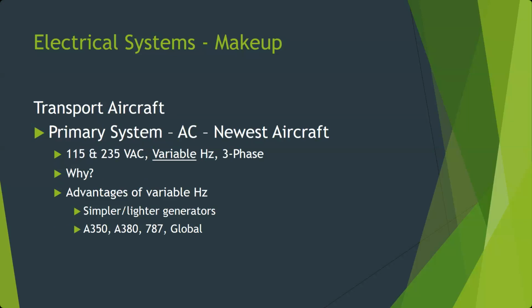What we've done is everything that can run off wild frequency in these aircraft now does run off wild frequency. What would need a specific frequency potentially? What might need a specific frequency? Things that are more sensitive, electronics, things like computers. And so what you can do though is now we have these really nifty solid state devices where before this used to have to be done with a mechanical drive and all that. That can be done in this tiny little chip inside of an individual component.